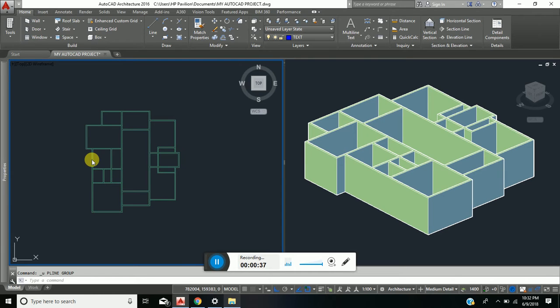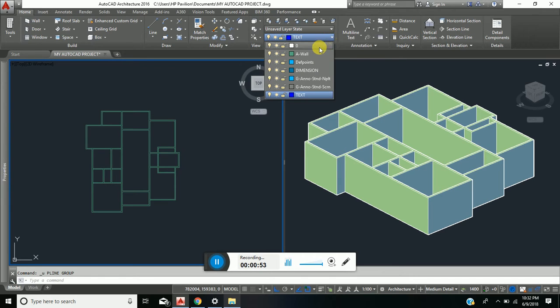I'm going to be basically drawing an outline around the portion of the building that we intend to be fitting with pitched roof. To do that, let me do that on the zero layer. I wish not to do that on a layer that I intend to be using.